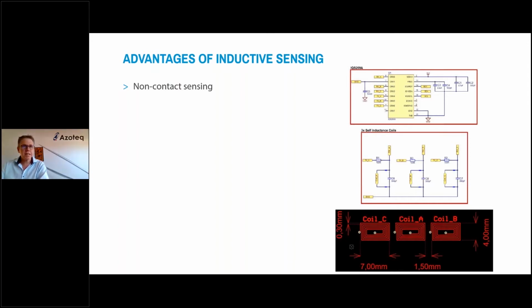Firstly, on the design side. Secondly, on the mechanical design, the mechanical housing, it simplifies the construction. And ultimately, it makes your application more reliable and more robust, since you don't have to worry about membranes that are wearing out, membranes that are cracking and allowing water in, or otherwise corrosion to the contact points. It is a purely contactless method with all the inherent reliability that you will find in industrial applications.